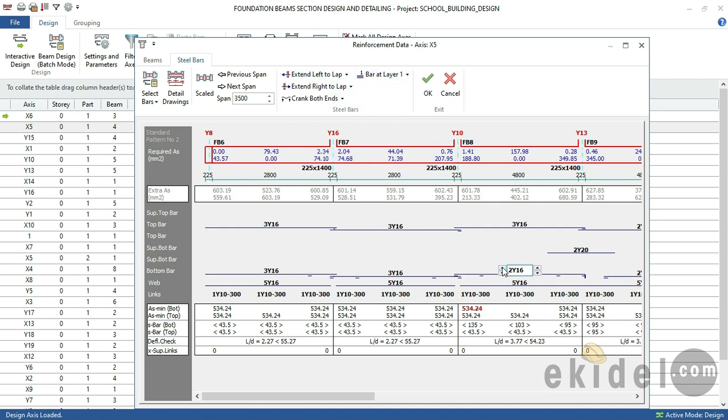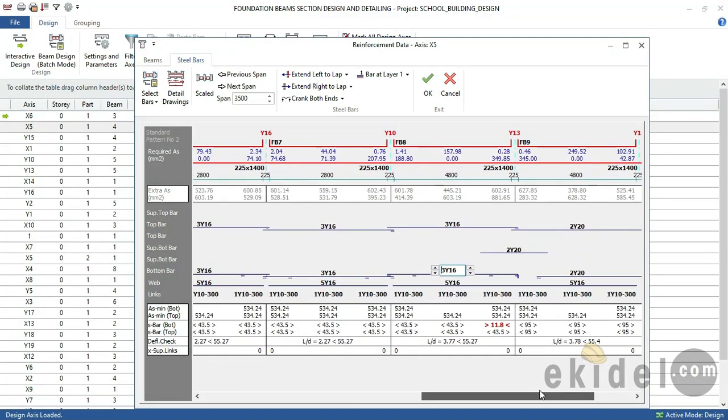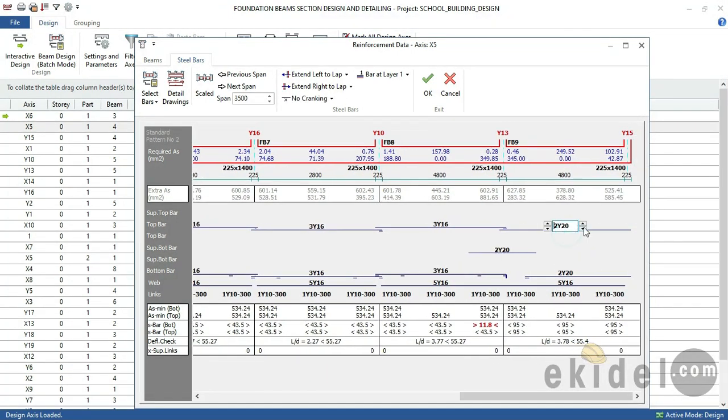Okay, so right now you have to increase here again the number of reinforcement, and then go and check again on this place. Come here, decrease the diameter, and then increase the number. When you decrease, there will be a failure. This red thing here means failure. If you print out your drawing like this, the building will collapse. So you have to increase to make sure that there is no red here, and also no red here.